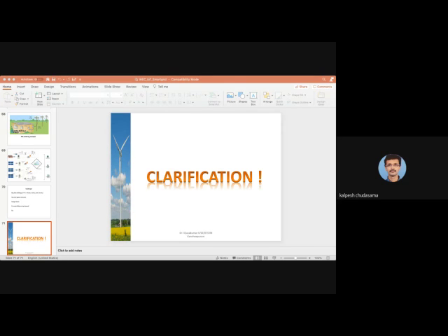Will it only collect data, or will it play on protection? It will collect the data and also play with those relays. Because the distance strategy is different in zone 2 and zone 3 step characteristics, mho and like that, different characteristics, by voltage and current. That is possible. On top of it, you are having the communication layer.